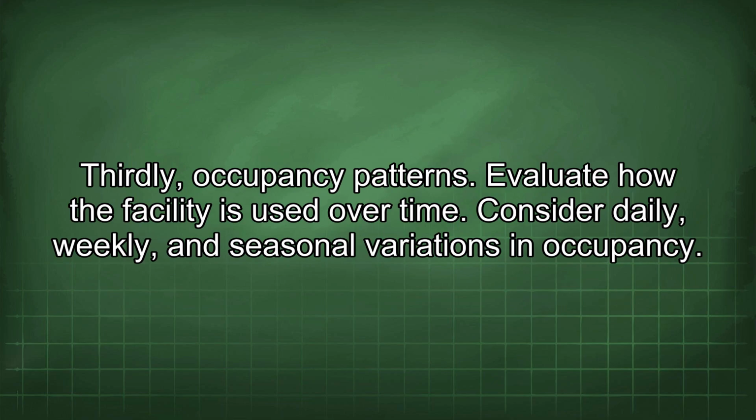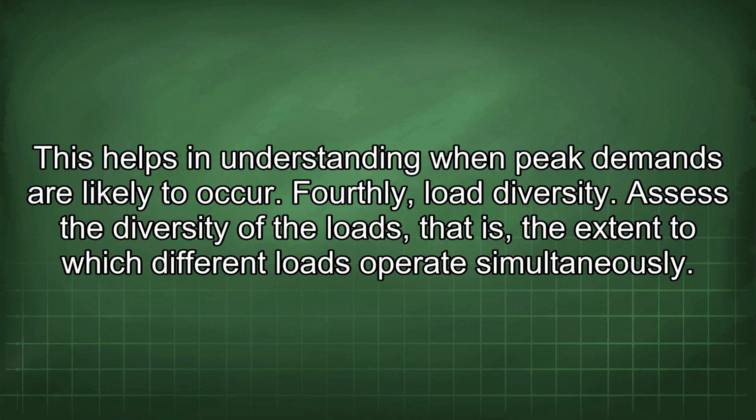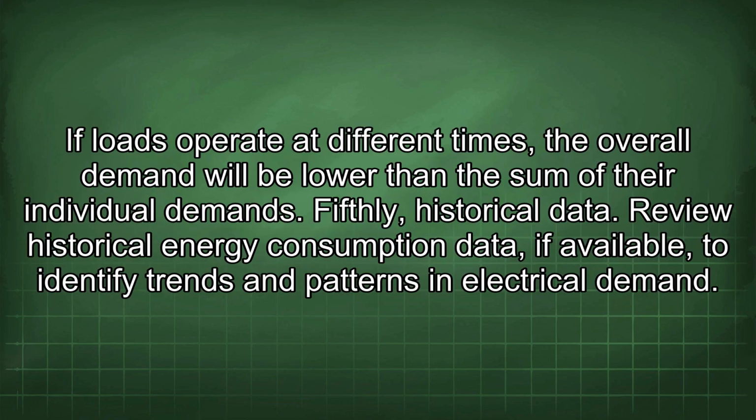Thirdly, occupancy patterns. Evaluate how the facility is used over time. Consider daily, weekly, and seasonal variations in occupancy. This helps in understanding when peak demands are likely to occur. Fourthly, load diversity. Assess the diversity of the loads, that is, the extent to which different loads operate simultaneously. If loads operate at different times, the overall demand will be lower than the sum of their individual demands.